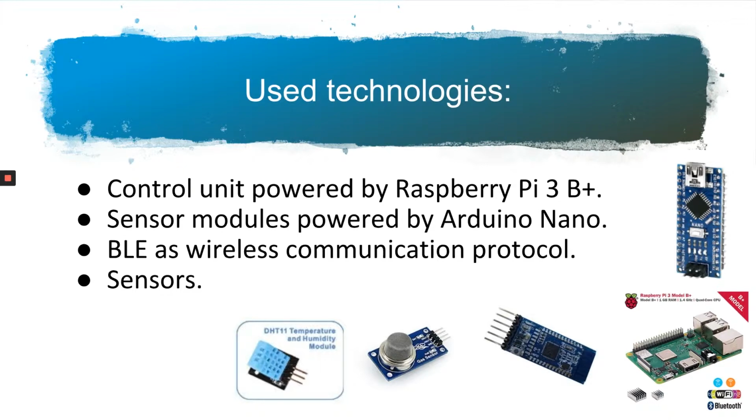For the sensor modules, we decided to go with the Arduino Nano board just because they're low power and capable of communicating to multiple sensors and serial devices, including the communication module. Another big advantage that played an important role in this decision was the size of the board, since it will allow us to have more freedom in the physical design, considering even the addition of a battery instead of a power cord that would limit users when placing them around the house.